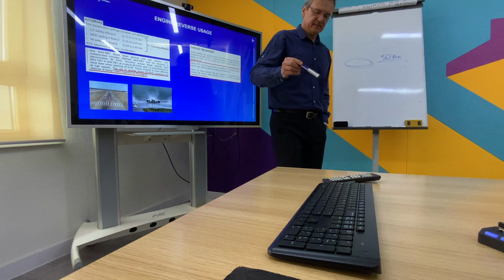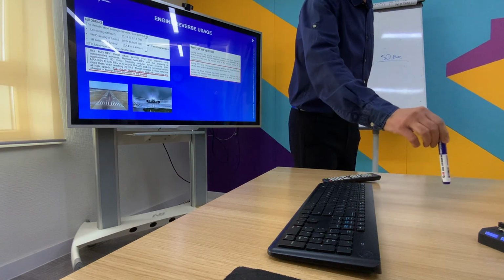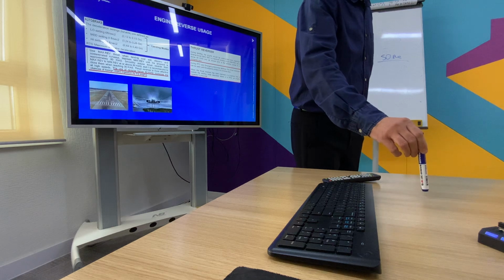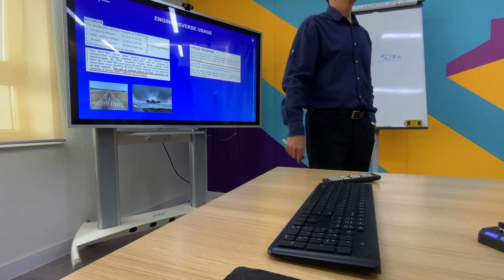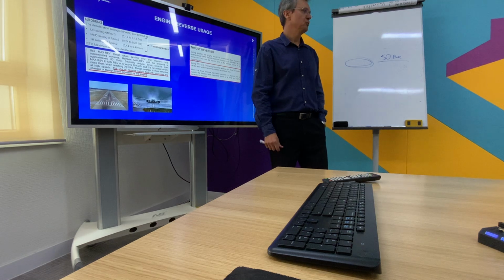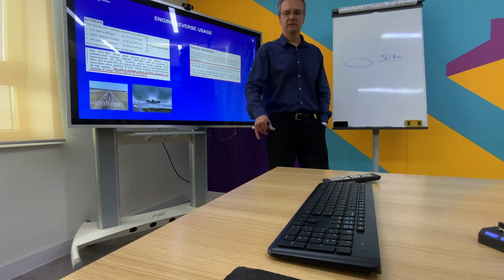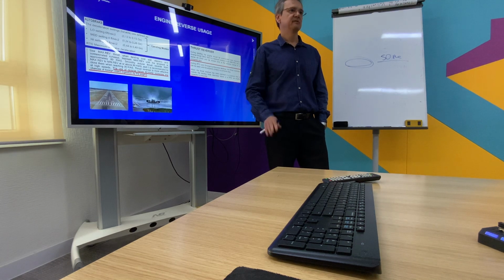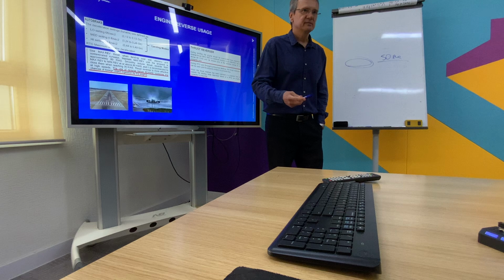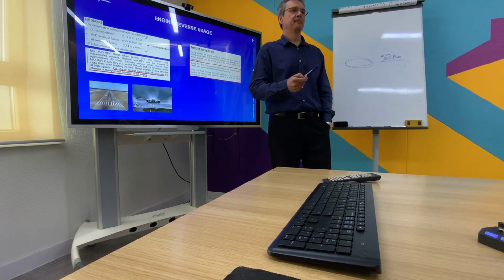Having that said, guys and lady, do we need to apply maximum reverse for dry runways? No need to do that. No need, only minimum. For dry runway, only minimum reverse. And doing that, you are saving engine life as well.